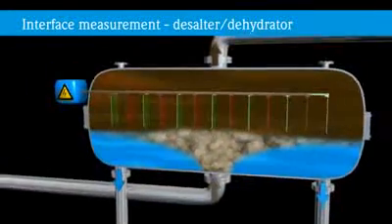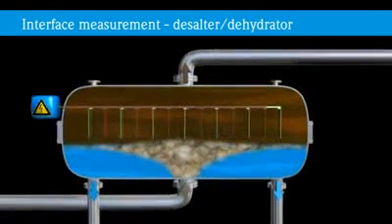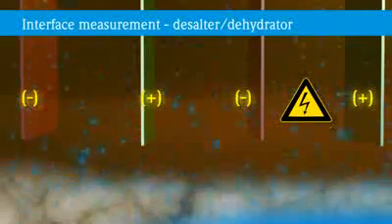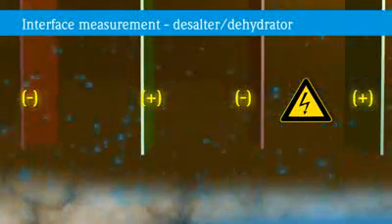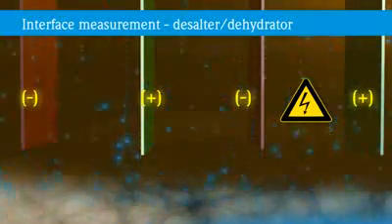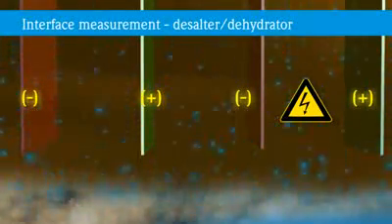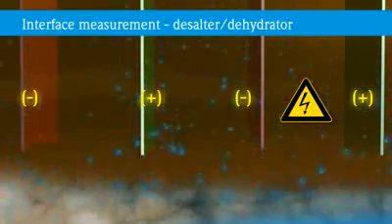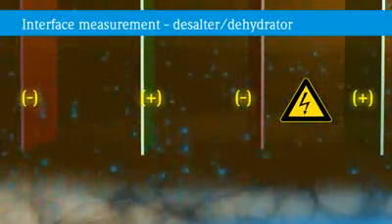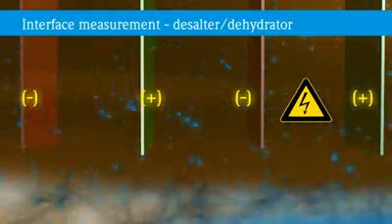The raw oil from the separator is often fed to a downstream desalting process in order to continue reducing the content of salt and water. The polar water molecules are aligned between the electrically charged plates of the desalter. This favors the coalescence of water molecules. Water drops are thus formed and moved downwards into the aqueous phase, once they have reached a certain size.